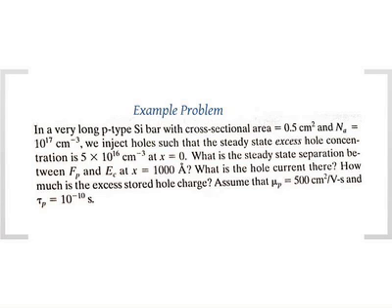All we need to know, let me draw the hypothetical diagram. This is the Fermi level, this is the conduction band. All we need to know is this number. That's all we're asking for, right? First part of the question. What do we need? Yes, we need the total hole concentration at x equals 1000 angstroms. That's it. Once you know that, you know everything else. Why?